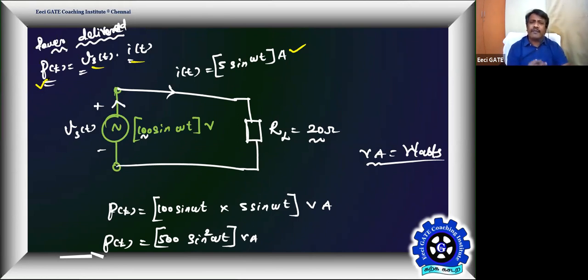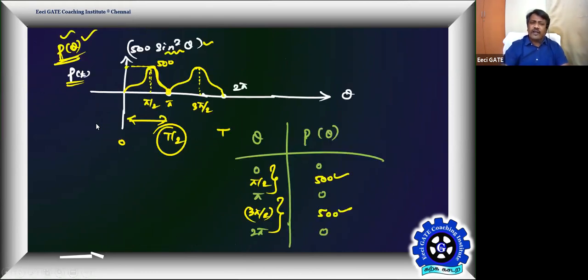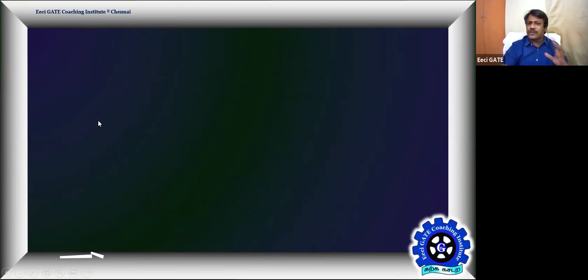In AC circuits, in general, what power we talk about is average power only, delivered by the sources. When it comes to DC, the voltage is constant, the current is constant, so the power profile is also constant. That serves as the average power. So whenever you talk about the power of a periodic signal, by default it means only average power. Getting everyone?